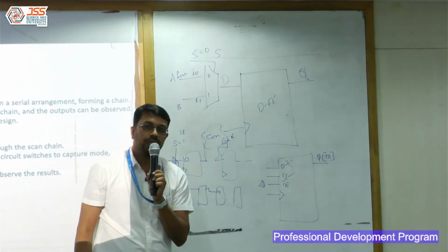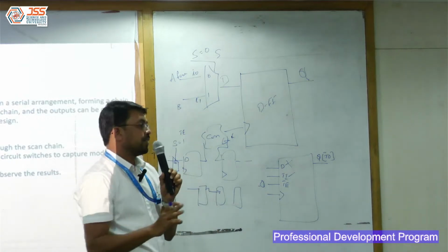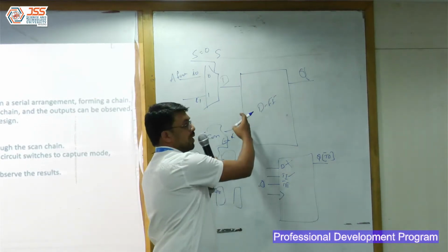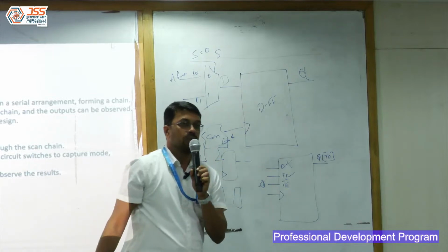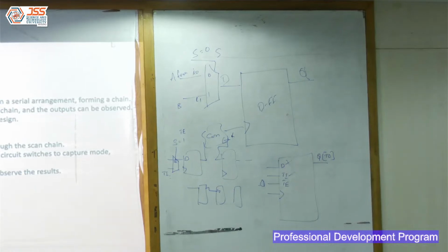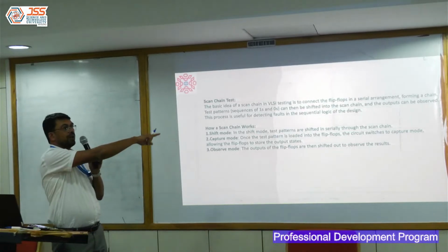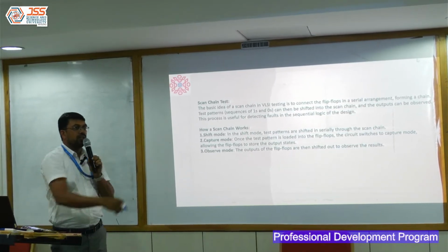So the first step that I do in my design is I swap all the regular flip-flops into such scannable blocks. This is the first step which happens during DFT. This is where the concept of shift comes in, because I was talking about a scan chain which works in the shift mode.